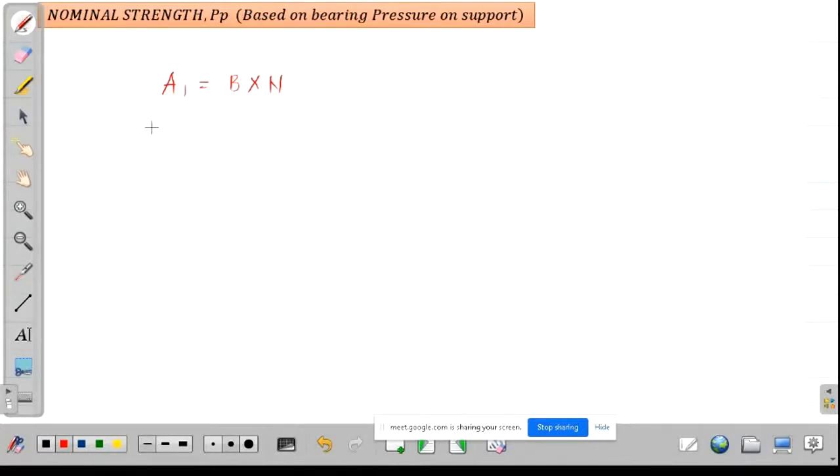So yung area natin, which is 137,901.31 mm squared, is equal to, let's say, B is equal to N, so B squared. So ano yung B natin? That is the square root of this value, that is equal to 371.35 in mm.